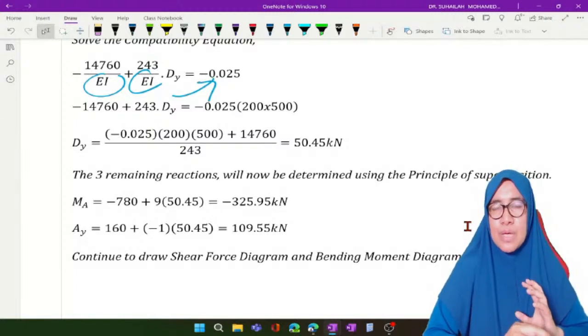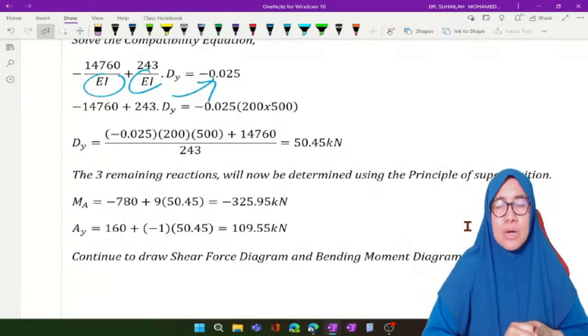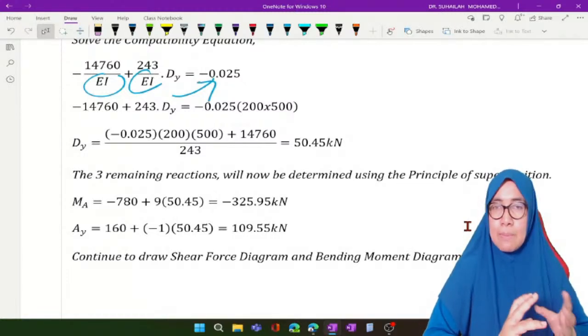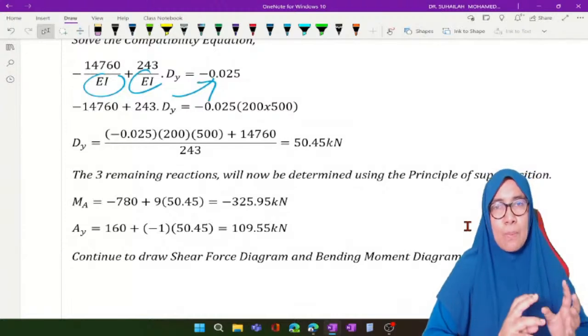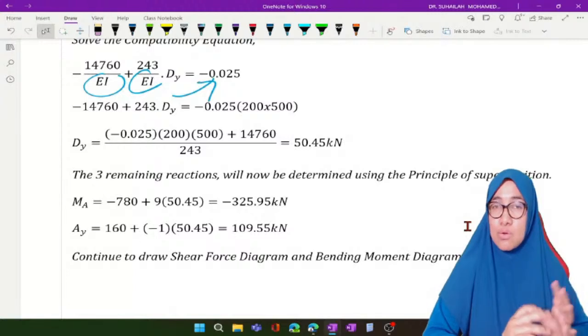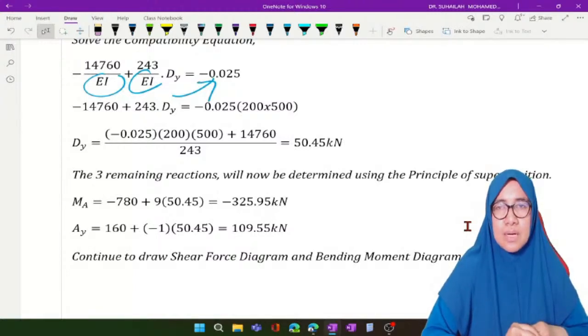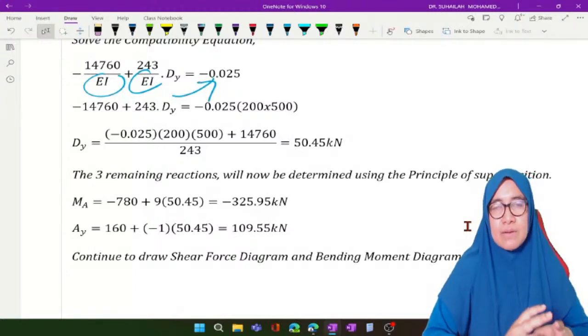We do not write moment equations in truss, but we have to find the member forces as internal forces in truss. So the table will be different because it will be based on the member forces, for the primary truss and for the redundant truss, and we have to find the total based on the formula. So please find the formula to calculate deflection in truss, because we use a different deflection formula whenever we analyze truss.